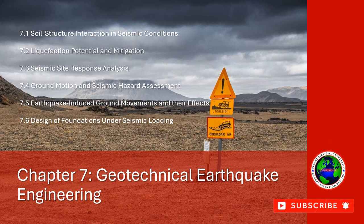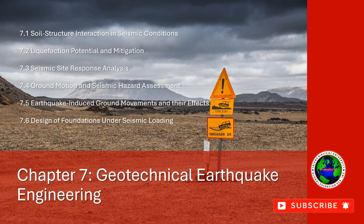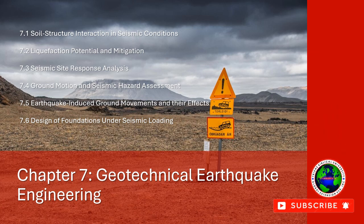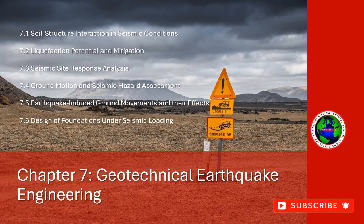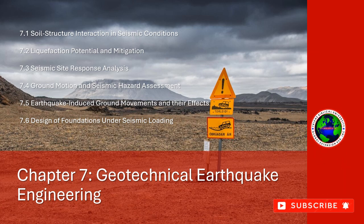3. Foundation stiffness and dynamic interaction. The interaction between the foundation and the soil during an earthquake is essential to understanding how forces are transmitted through the system. Foundations that are too stiff may amplify seismic forces, while excessively flexible foundations may undergo excessive movement, leading to structural damage. The foundation must be designed to balance stiffness and flexibility to minimize the effects of seismic loading.